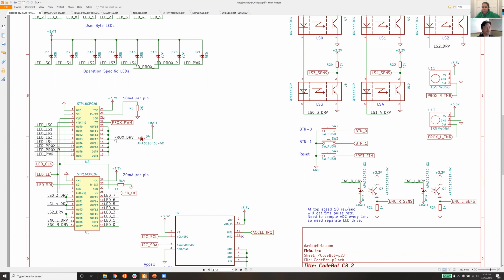And this whole shift register thing, currently, if you've got a CodeBot, it's controlled down in BotCore, and BotCore uses an underlying library that uses a SPI peripheral, a serial peripheral interface piece of hardware that's inside the STM32, to control those really fast. So I think it's clocking at 10 megahertz. So it's clocking really fast, and nearly instantaneously you get 32 LEDs set.